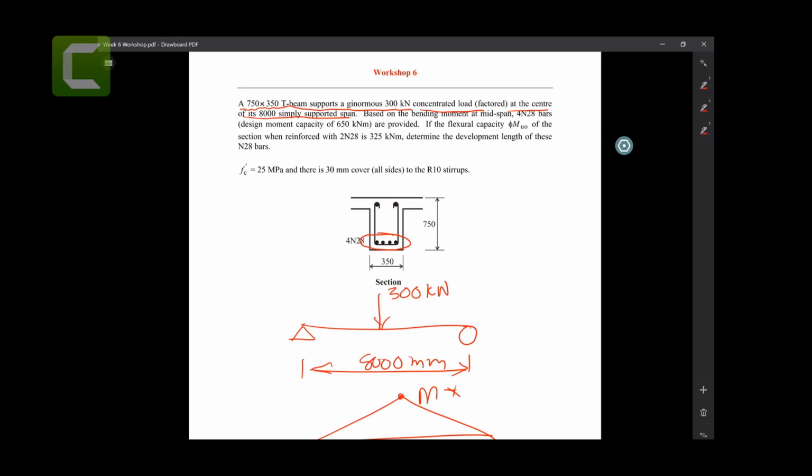Shear is not that problematic. The beam generally has no need to be redesigned for shear unless you are very near the support conditions, where there is a high shear zone. Generally, the beam needs to satisfy the bending check. When the bending is okay, shear is okay, and we just go for the development length.